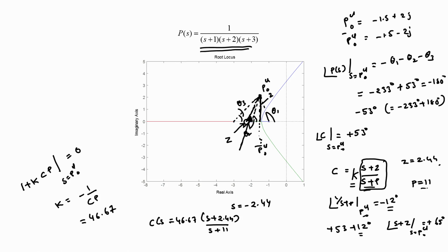and this completes our design. Note that our closed loop poles will not be located only at these two locations. You have another branch of the root locus also on this side, and therefore you will have a closed loop pole also lying on that branch. But since that pole is much farther away from the origin compared to P_CL0 and P_CL0 bar, it will not dominate the dynamics of the overall closed loop system, and therefore we do not need to worry about its exact position.